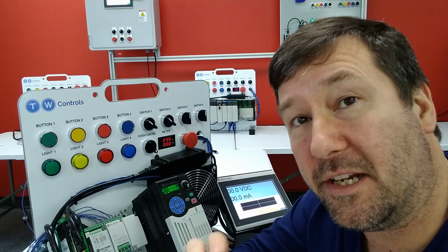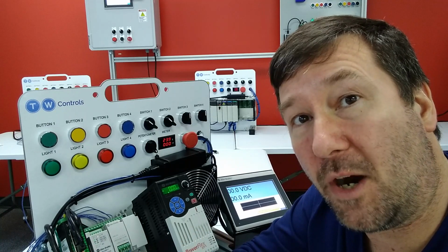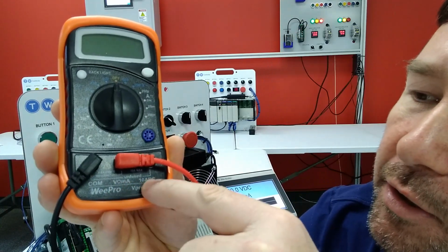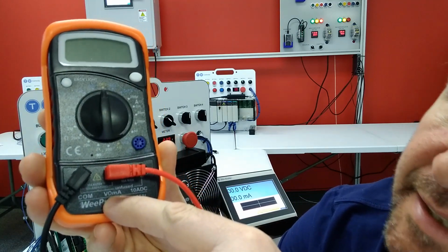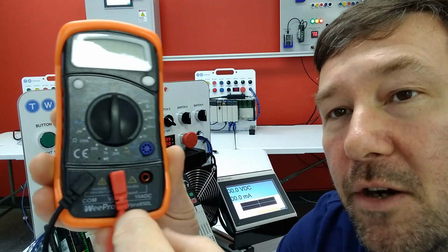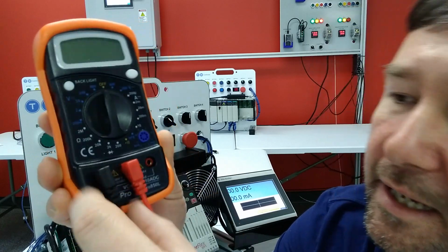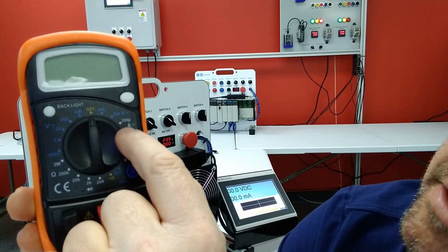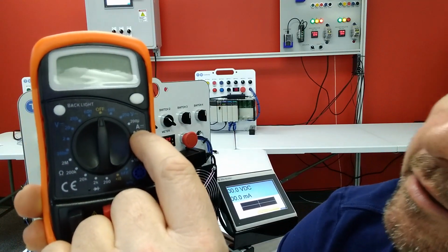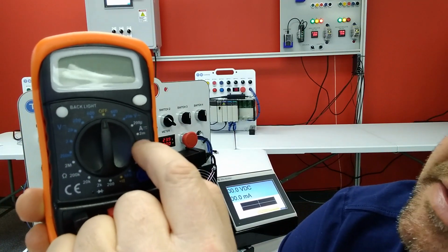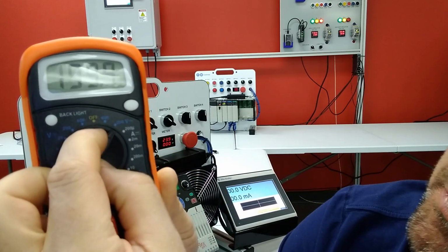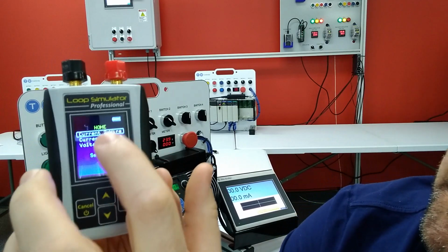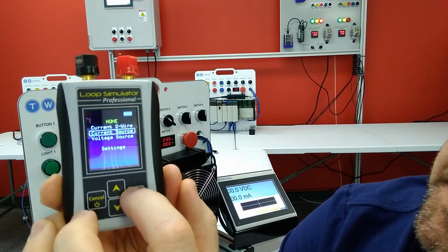Let's start by simulating a current source, or a 4-wire device, to a basic multimeter. If we look down here, our middle post says mA for milliamp. So that is where our red post needs to be. And then our black post will be on the common. And we want to go over here to the amps DC area, but we want to make sure we're on these milliamps. And I'm going to select 20 milliamp. And then on the ALP2, I'm going to select current source mode.